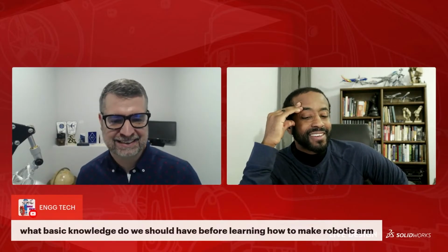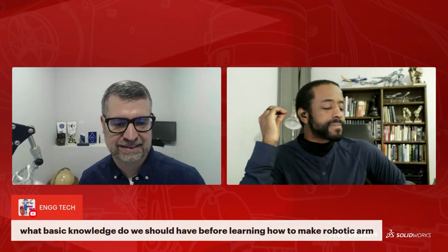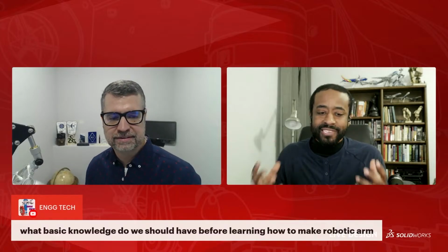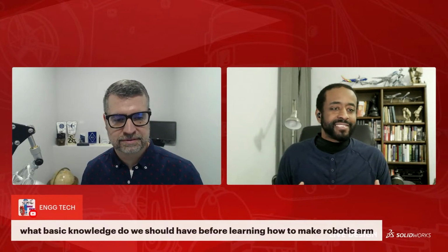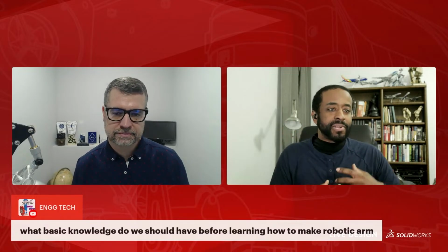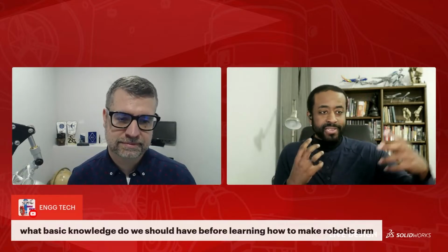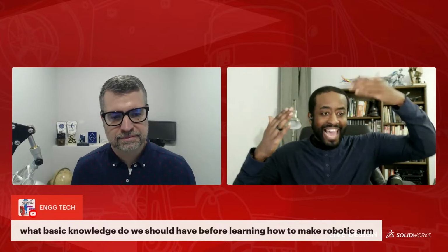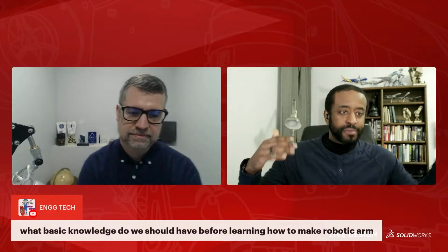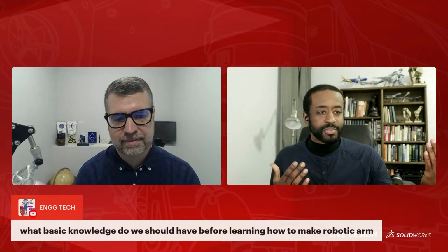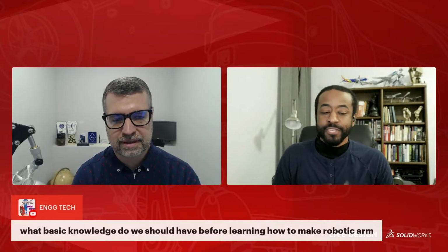I think a better way to think about it would be, do you have the mechanical design background to at least make something that won't shake itself to death, that you can think about moving a design that has moving components, remembering that each axis is dependent upon the one below it. So if there's any play in the first axis, that's going to be added to the play in the second and the third and the fourth and so on. So any error will multiply throughout each axis. So your mechanical design background needs to be really solid.